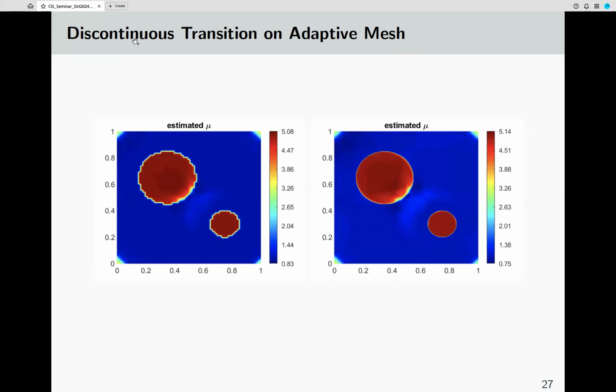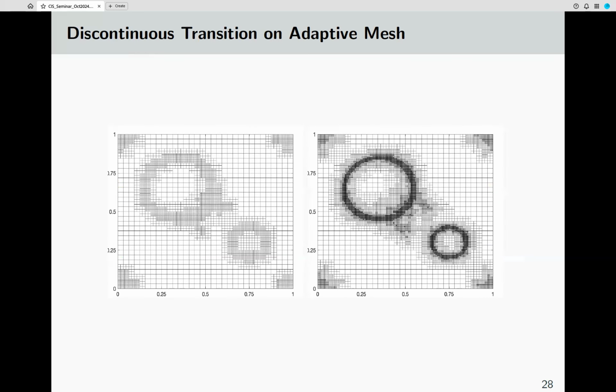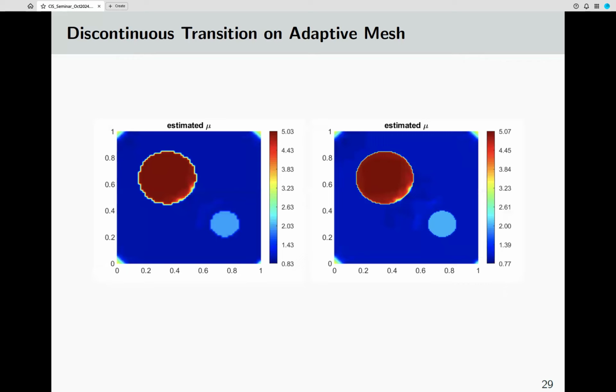And that can be done by using something like this. This one corresponds to adaptive mesh refinement. Here it is at some point before you stop and you're happy with the solution. And this one is how it looks if you use a mesh that I'm going to show you in the next slide. Here you see that it is refining the mesh much better right around the boundaries, right? And in other places, it's almost coarsening. That's how you resolve these, right? So you definitely get better accuracy with a smaller dimension of the optimization problem.